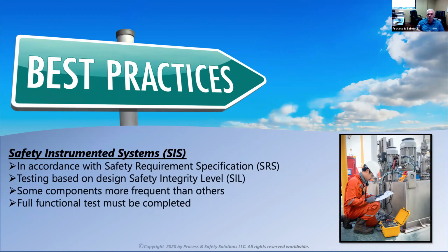So make sure that you refer back to your SRS, or safety requirement specification, to find what that is, and then you must test and inspect those devices in accordance with those frequencies. No matter what, a full functional test must be completed. A full functional test is from the input to the final element, or the output device.